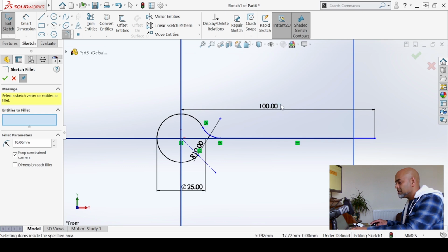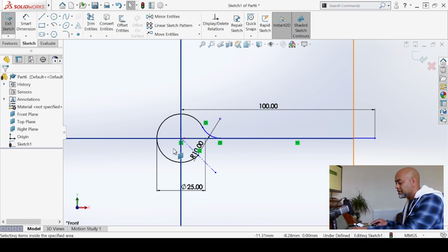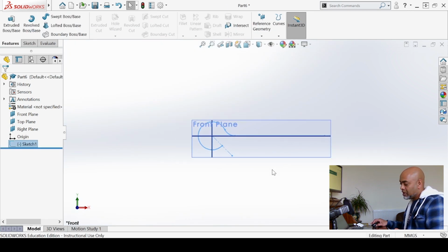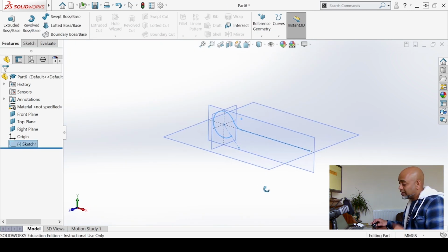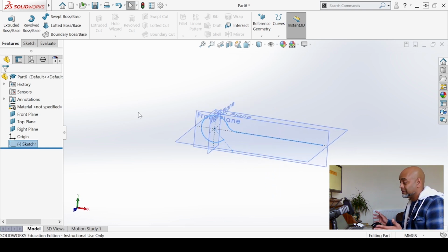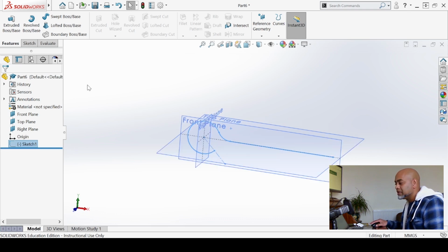Okay, all I did here, just to summarize, I created a circle, a straight line, and I trimmed away the area I didn't need, and I blended both of those together to create a wire shape, a hook shape like this. Okay, now what I want SolidWorks to do is extrude that out for me. Now you're thinking, this is not a closed compound. How will it? Well, it will work. It will work. Right. So when that's pre-selected, I'm going to go into Extrude Boss Base.